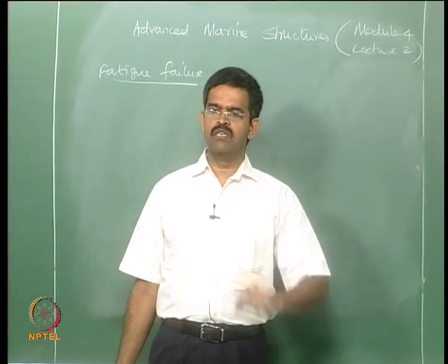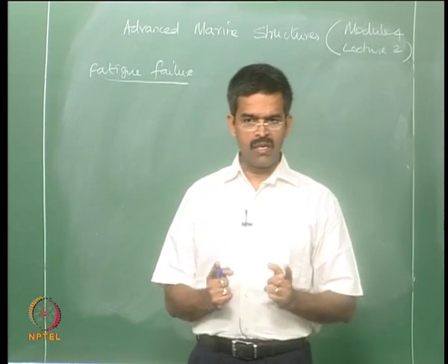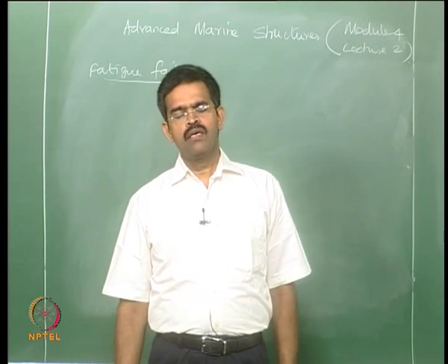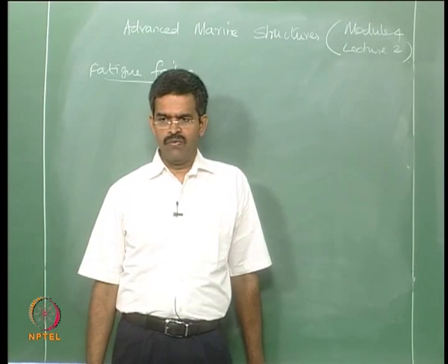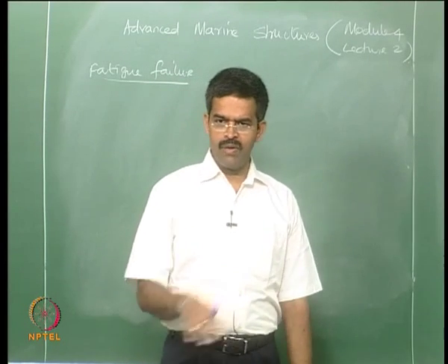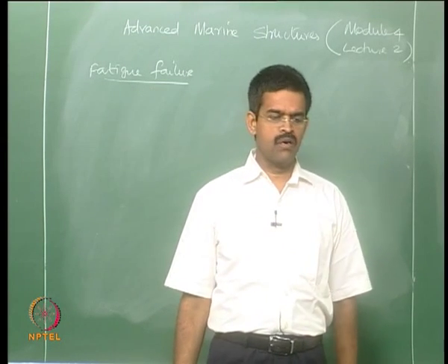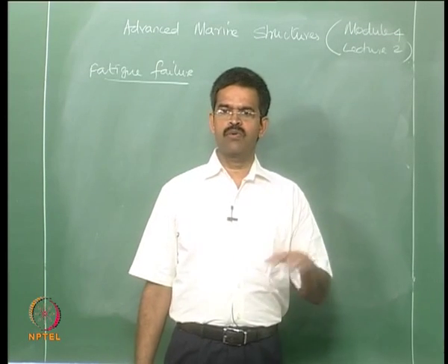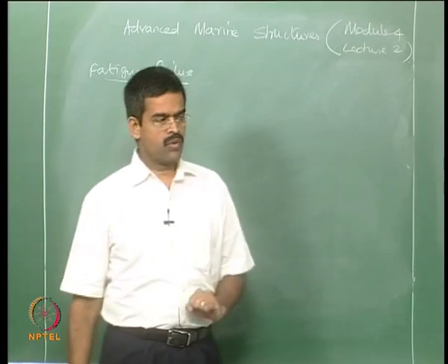that the stress variations or fluctuations are in a specific state or in a specific range, and this is caused by the range of stresses applied on the material or on the machinery for a given design life, and one can easily estimate it by limiting the stress levels within the endurance limit. Whereas this concept cannot be applied to marine structures, because in a marine structure there is a mixture of different kinds of stresses and fluctuations happening, and therefore one must estimate it in a different manner. Okay.